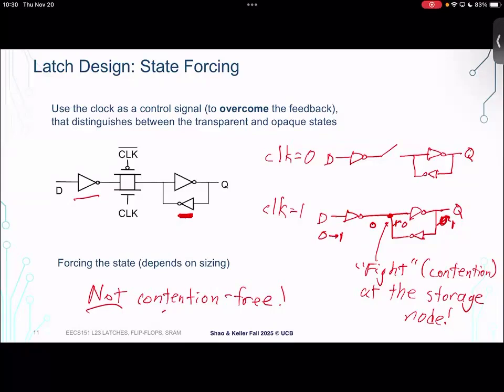As we're going to see more when we talk about SRAMs, when you start to have these very common state elements that are repeated many millions of times in a design, it's worth being more aggressive or more deliberate and moving away from the abstraction of ones and zeros within the cell.